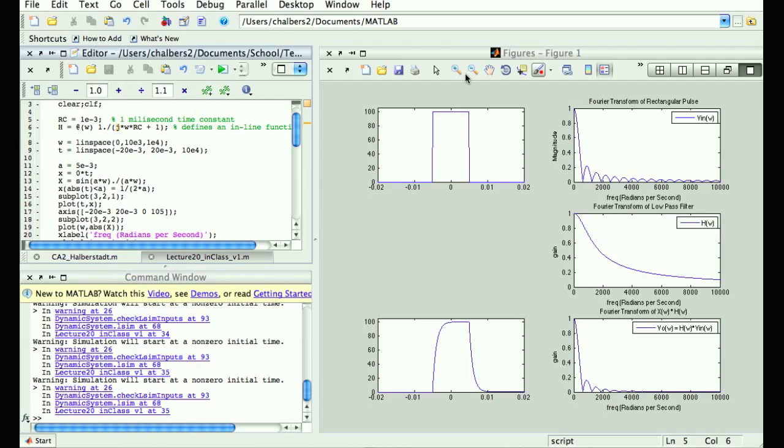How come we're not seeing a constant 20 dB? Because in order to see the 20 dB per decade, your x-axis has to be logarithmic and your y-axis has to be in decibels, which I'm doing neither of.